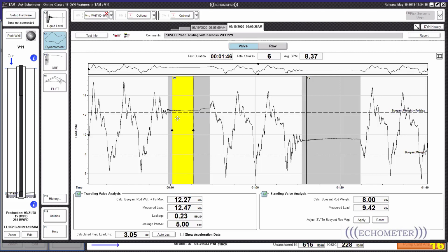Well, as big as you can have it. It's not something we would recommend, because you cannot input that. You need to properly size your system and run it in the most efficient way possible. You don't want to over-dimension your pumping unit, your motor, or your pump, so that you have a partially full pump.